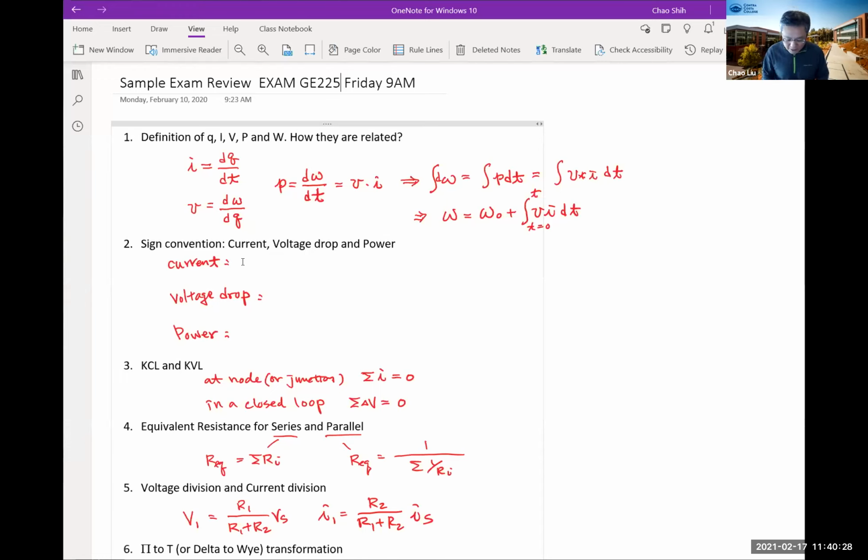A capacitor always gives you a voltage drop because it's from high voltage to low voltage. Whenever you see a capacitor, and if you know the direction of the current, then the end of the capacitor where the current goes in is always positive. The other end will always be negative. That is the rule to find the direction of the current and also the voltage drop of the capacitor.